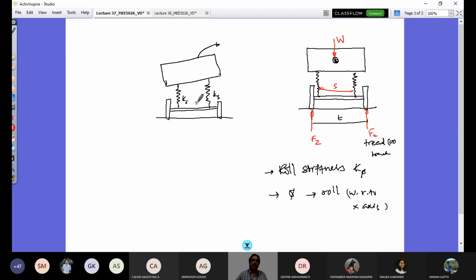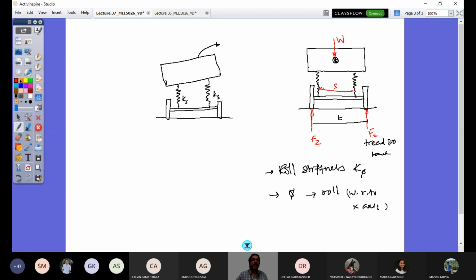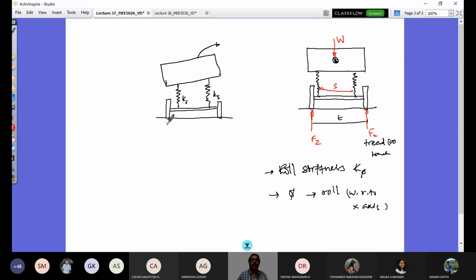So now let us look at what the free body diagram is going to be. I have here F_zs, and I will call this F_zs with the subscript o, F_zso, the outer side normal load, and I would have here F_zsi. If you see, this length is smaller than this length, so this is longer because of the load transfer on this side. The magnitude of the outer normal load is more than that of the inner normal load. It is equal otherwise if it is not taking a turn.